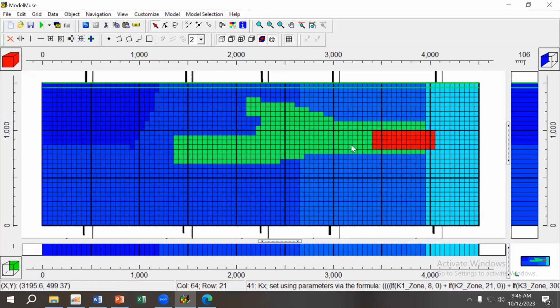So let's start with the recharge. How could I define recharge? I'm telling you in the project description to assume that recharge is constant over your model domain. You have one constant recharge. For your model application, that recharge will change, because I will tell you that you will have an industrial zone that will plug recharge. Recharge will be zero because you have impermeable pavement or something. But for the case of constant recharge, I want to define the same recharge everywhere.